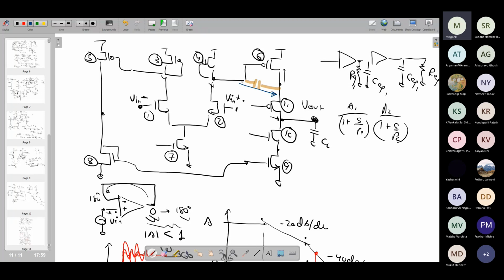The mechanism is that here it is propagating the signal in the non-inverting way, whereas this path is propagating the signal in the inverting way, and therefore if it cancels out at frequencies where these two signals become equivalent, it leads to a zero. That is the mechanism for a zero. So whenever you have paths in the circuit where there is a possibility of cancellation between the feed forward and the actual signal, you may get a zero.